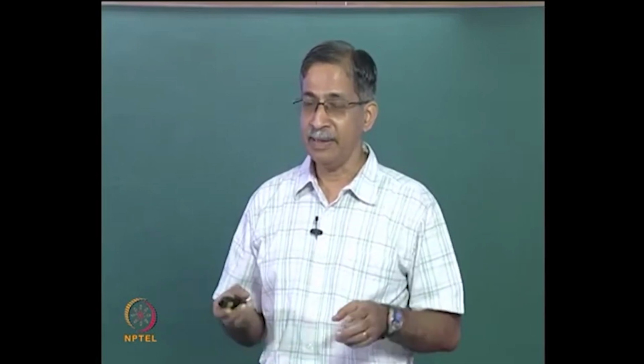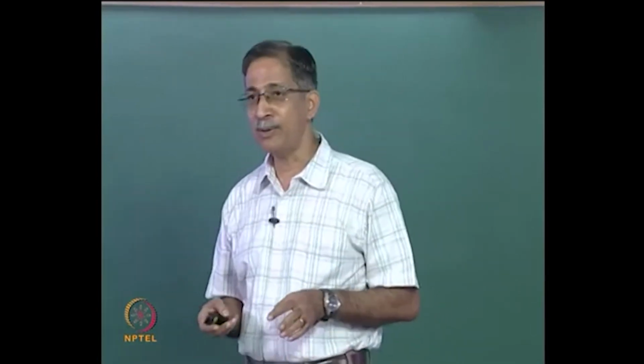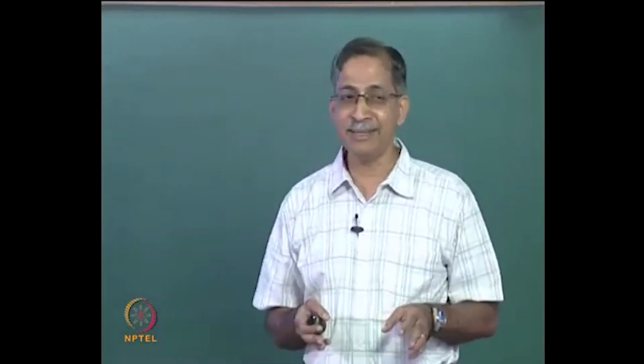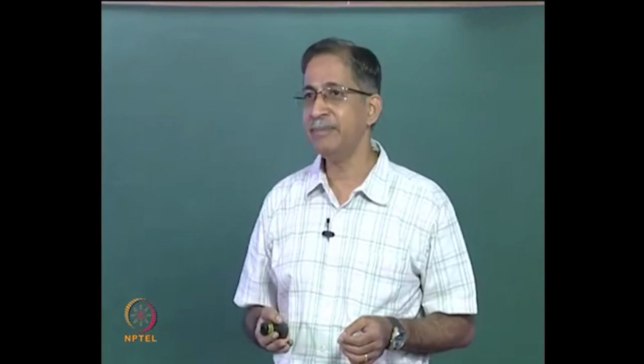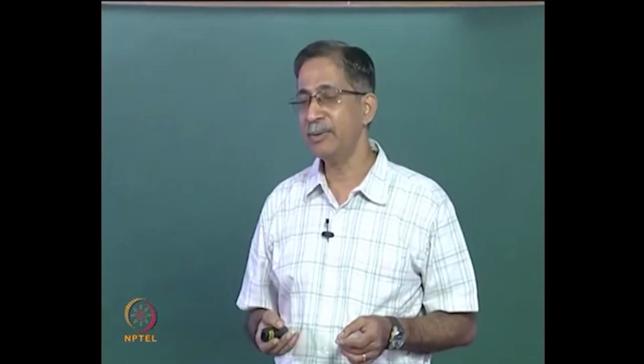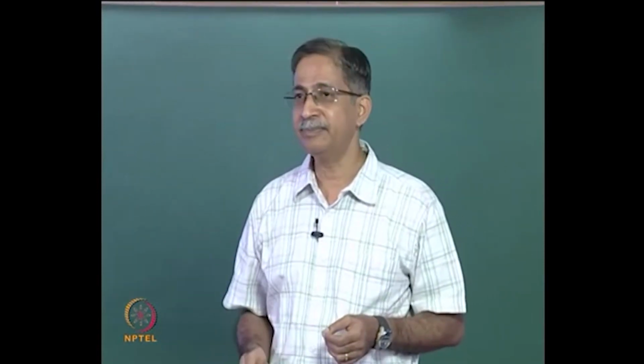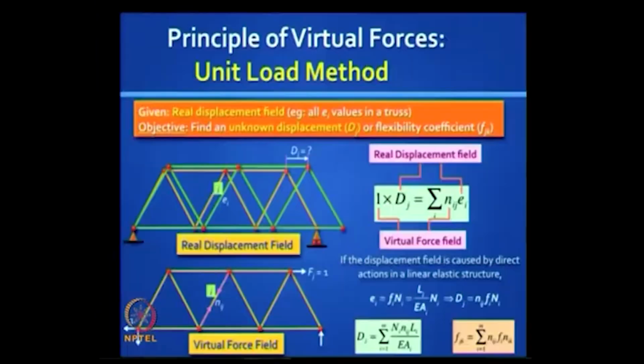Now if you are finding the unknown displacement in the loaded structure, here we are making the assumption of linear elastic behavior, because the modulus of elasticity comes in here, and so you will get this form for a truss, and you can now pull out the definition of flexibility coefficient from here.